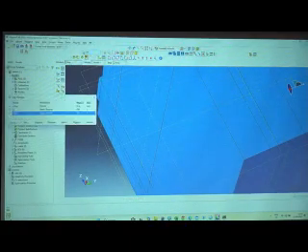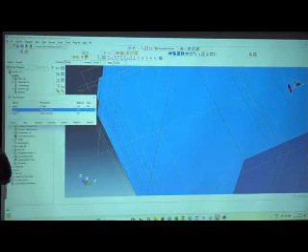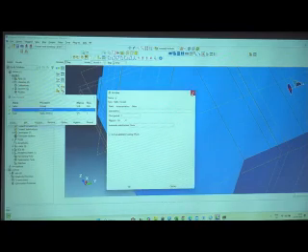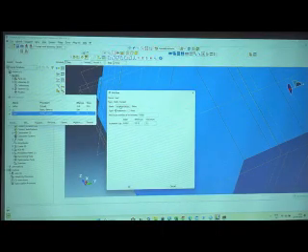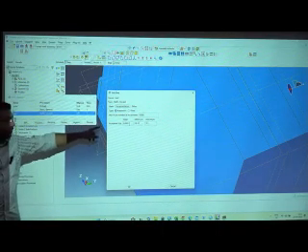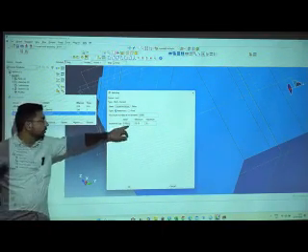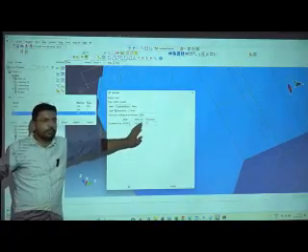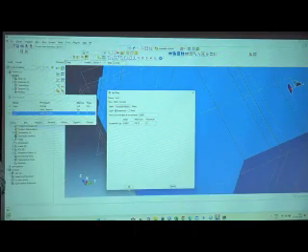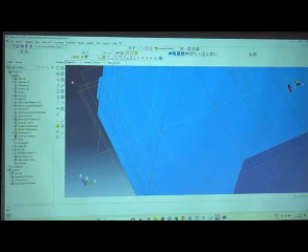After this, there is a step. There is an initial step. Then to apply the gravity load, I choose the general static step. Then to apply the final load, I again choose the general static. I have changed the incrementation. The time is 1 second, the initial increment is 0.001, the minimum is 10 raised to power minus 10, and the maximum is 0.1. After the step, the interaction part comes.